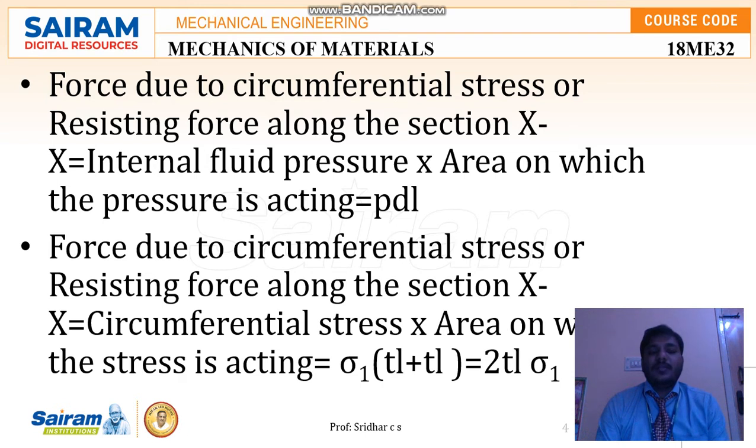So the force due to the internal fluid pressure will be equal to PDL, that is, internal fluid pressure into the diameter along with the length. This is how we identify the bursting force. Next, the resisting force along the section XX: it is the circumferential stress into the area on which the stress is acting.